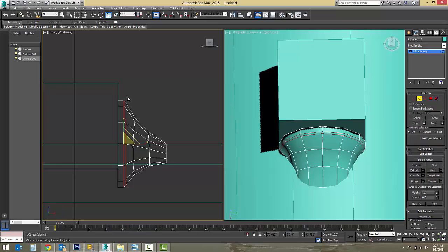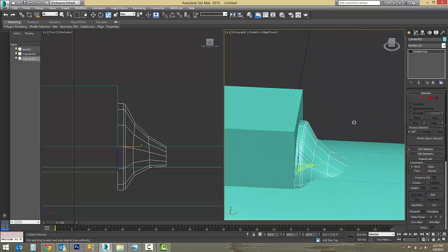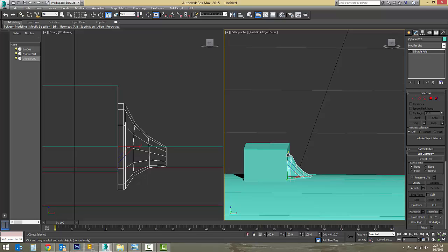And this is still not enough of a curve of what I want. So you can either marquee Control Select, or you could just grab one edge and hit Loop, and it'll make a loop in the circular motion. We're going to scale down, and now we've got a curve here. I don't want to model this twice, so what I'm going to do, it should be a little bit taller, I think. So dragging up in the X-axis.